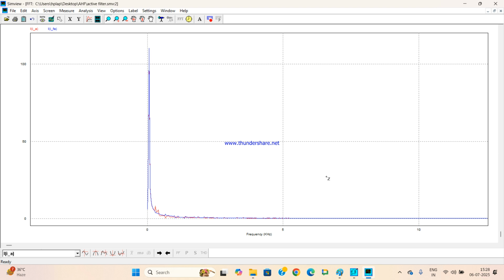Then how to find out the harmonics mathematically, that is the Fourier series expansion, which I told already. And then you talk about the passive harmonic filter. It's very simple to design. It's an LC circuit where the resonance frequency of the LC circuit is taken as the harmonic frequency which you want to drain. Based on that, the formula I have shown you, omega 0 is equal to 1 by root over LC.